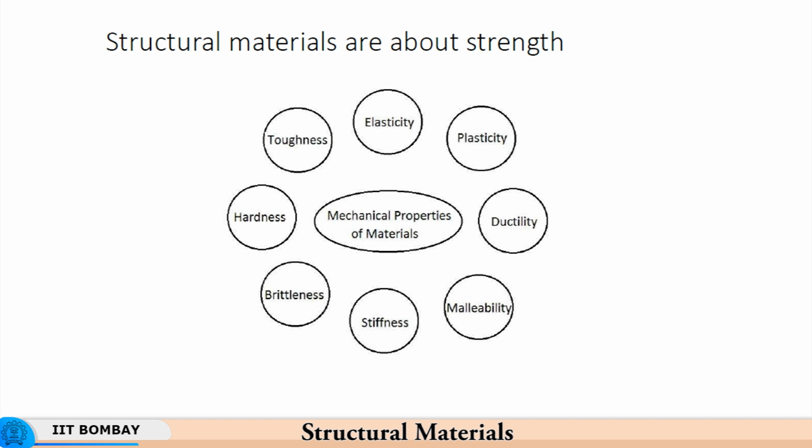So, what we mean by stiffness is load per unit deformation. That is what we call stiffness. Both the springs will recover their deformation, both will come back to their original position after the load is released. But the load required to deform the spring elastically will be higher when the spring is stiff as compared to when it is compliant or less stiff. So, stiffness is a very important part, particularly when you talk about machine structures.